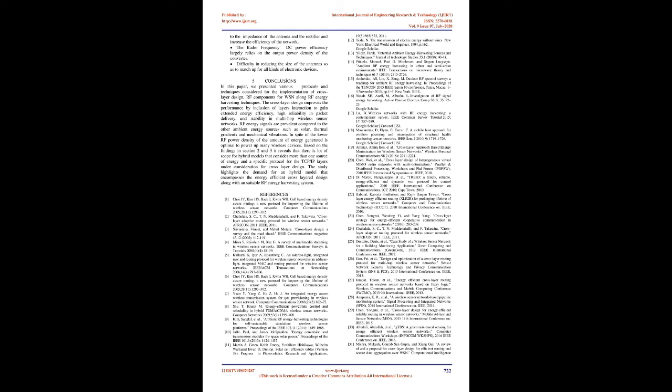Zhang et al. 2014 proposed a rectifier circuit to generate power from the surrounding energy sources with a shunted Schottky diode to achieve a maximum efficiency of 81%. The PCE attained is around 50% of the input power level at 25 mW for a frequency of 1.43 GHz.